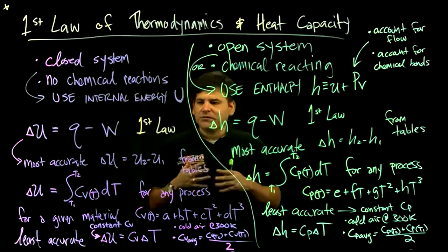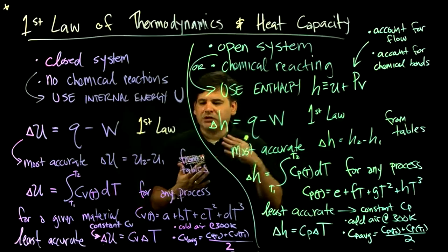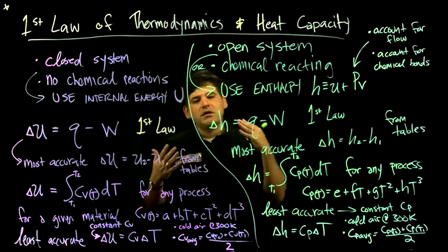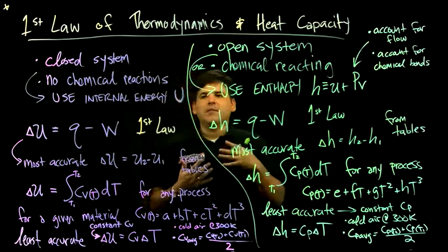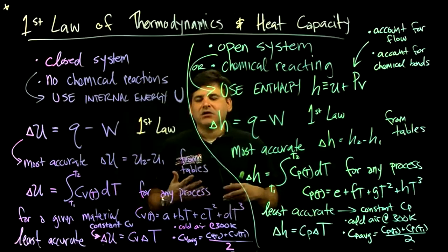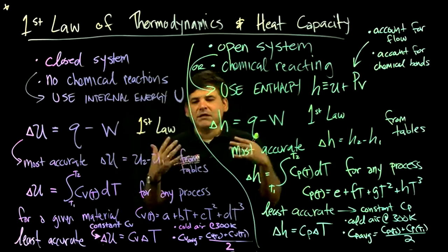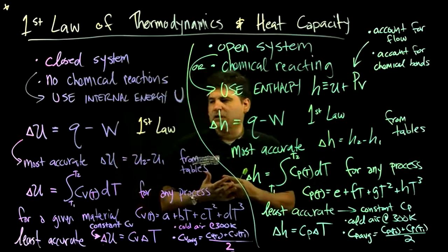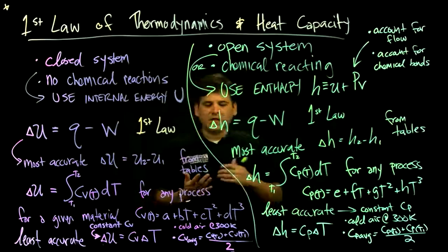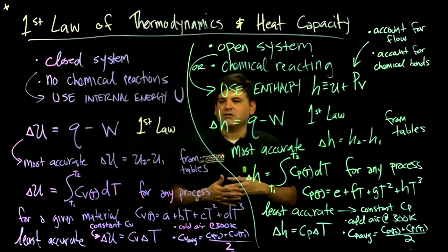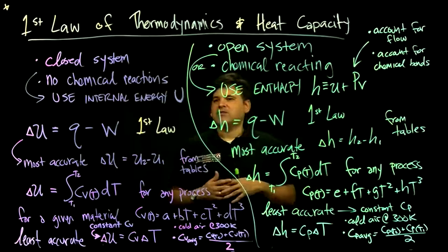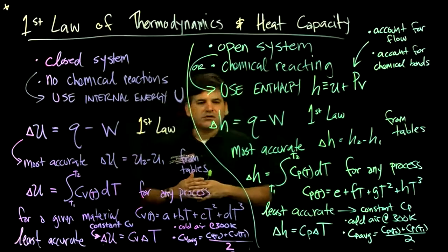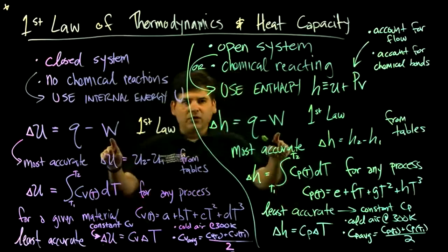It's always going to be related to a pressure change and a volume change, but when you have an ideal gas, you can get more explicit equations for this work transfer depending on the conditions, whether it be constant temperature, constant pressure, constant volume, or no heat transfer. Those are other scenarios which we will save for another video.